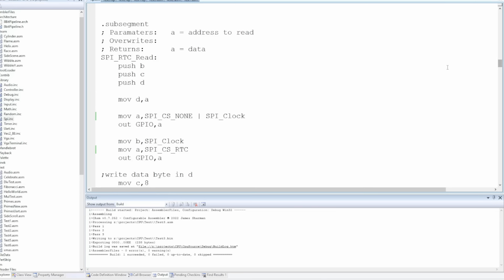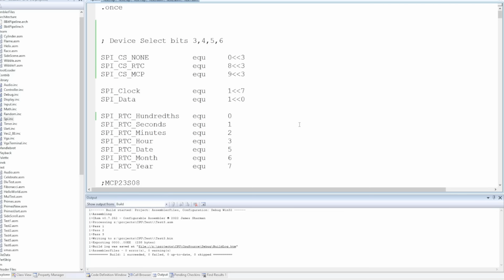Ignoring the other elements of protocol difference between the RTC chip and the MCP chip, this opposite phase of the clock is a significant difference we have to deal with. And in terms of what we want the shift register to do, the difference between loading on a high to low transition as it is at the moment to working on a low to high transition for the MCP chip, which is of course what the shift register actually does before we inverted the signal. So what we want to do is make that inversion conditional, and we're going to do that by adding a control line.